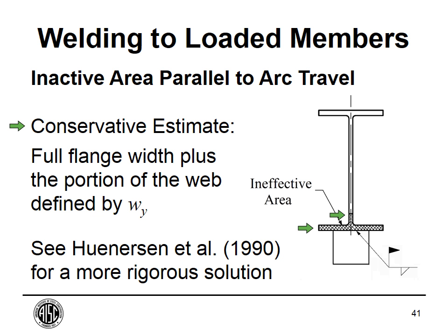And actually I've done this method. I just knocked out the whole flange every time I've done this, and my plates are located so far from the maximum moment that it's worked every time for me. I haven't had to go in and do the more in-depth calculation.